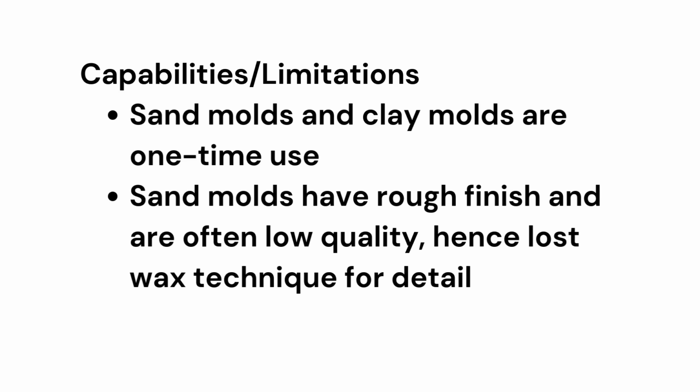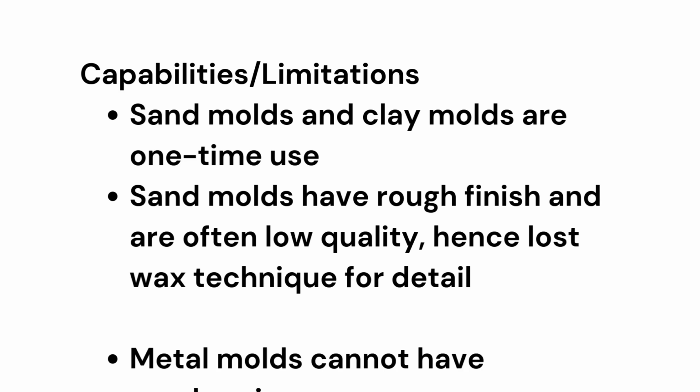Also, for the more permanent molds, the molded parts have to have some direction to them, i.e. no overlapping. The two sides of the mold have to move straight apart from each other so that the part can be removed. That's what gives the sand molds their advantages, as the sand molds don't have that problem. The mold is going to be broken anyway. It can be removed from whatever part is made.